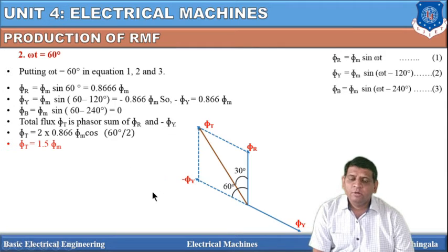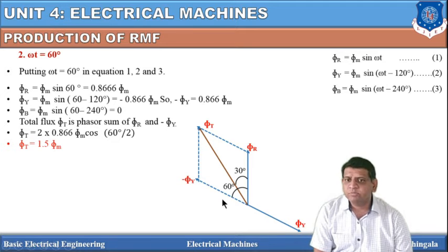What we are proving is how the magnetic flux rotates in the three-phase induction motor. The magnitude of the flux is the same, but the position of the vectors, the position of the magnetic field, is continuously rotating. At omega t equal to 60, you can see a slight rotation in the clockwise direction.